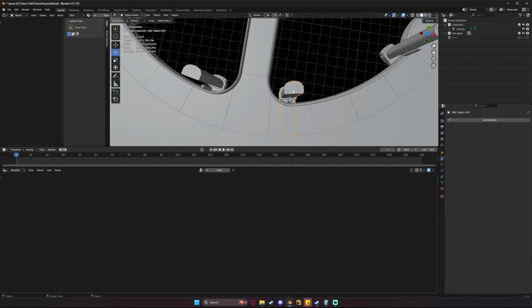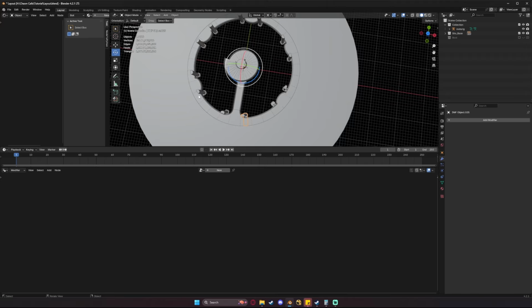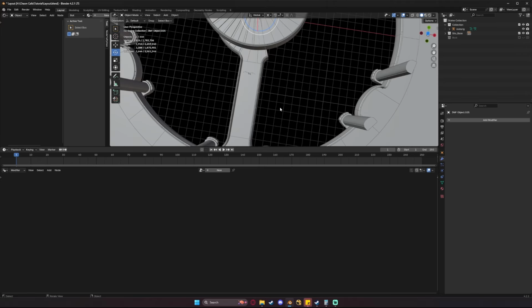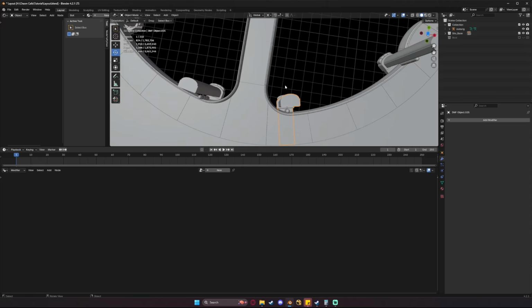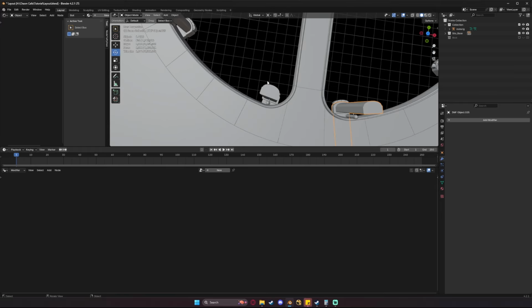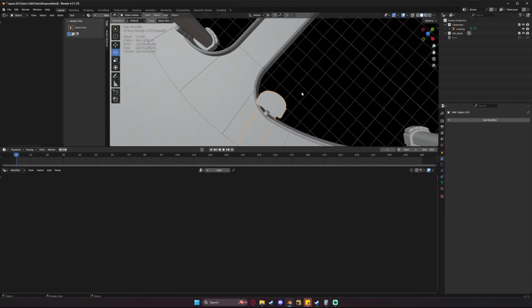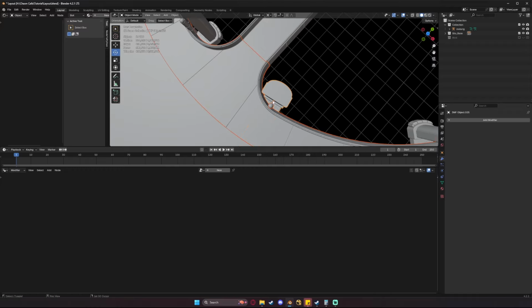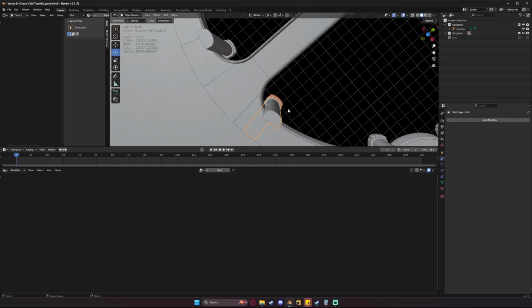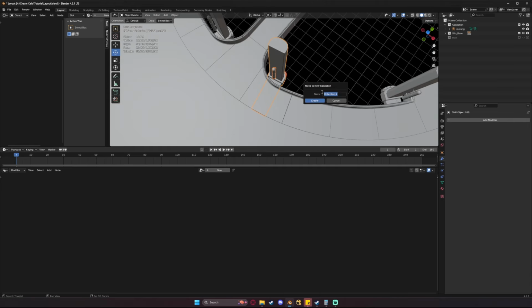We're going to join these two pillars together, and then we're just going to instance them around in a circle. And honestly, even easier than that is I can take this one pillar, instance it here, and then take that group and instance them around. So I think that's exactly what I'm going to do. I'm going to start by taking everything that's just here in this pillar area and not selecting the ground, and we'll make sure that we have everything selected. We do. And I'm going to move this into a new collection, and I'm going to call this pillar.